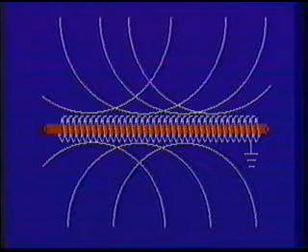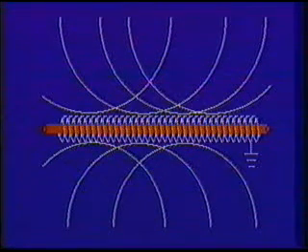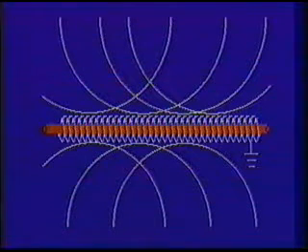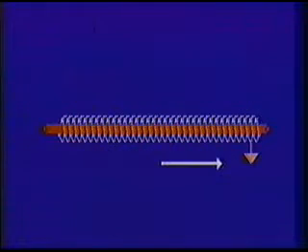Briefly, the theory behind this function is that harmful radiated fields are absorbed by the shield and harmlessly routed through the one grounded end and dissipated into the aircraft structure. The signal cannot re-enter the shield because it does not see another ground and there is no complete circuit.